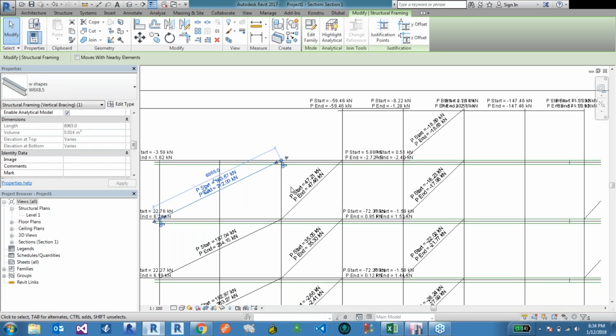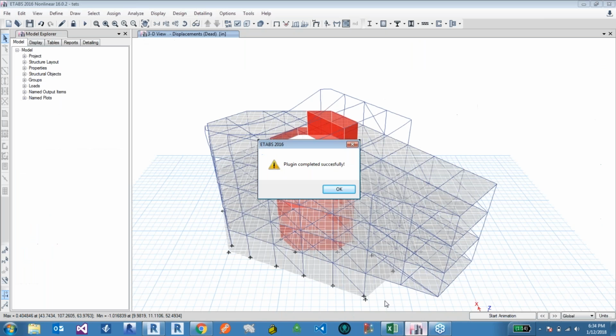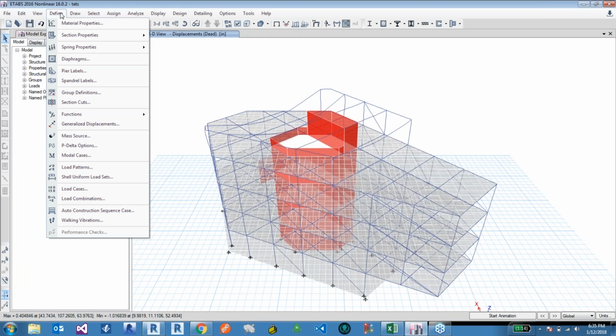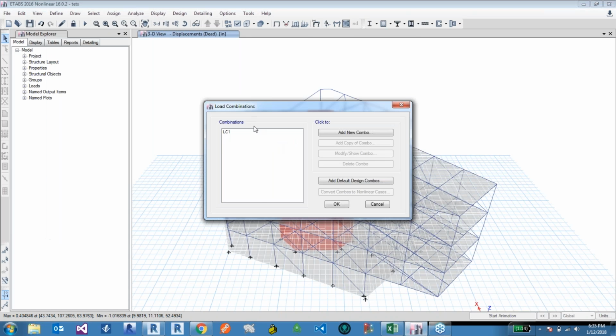And then we have another question. You illustrated a sample load combination. Could envelope results of multiple LCs be brought into Revit through Konstru in the same procedure? You can also use envelope results. That's not a problem, but you have to select one load combination. So this depends on your setup. We are limited to one load combination that we allow you to upload here.